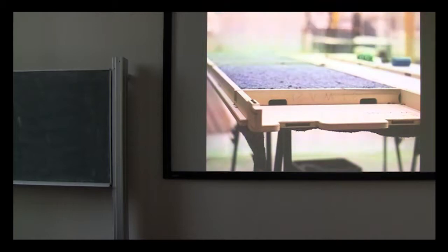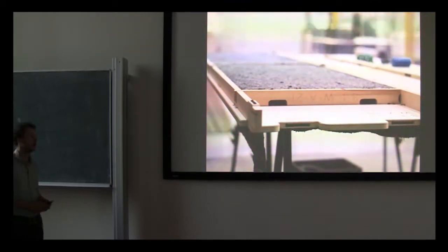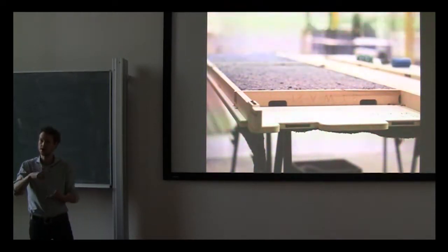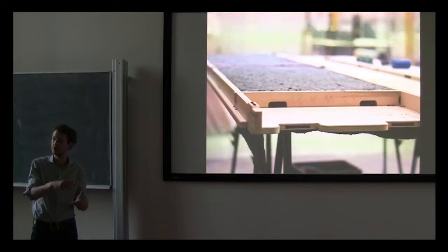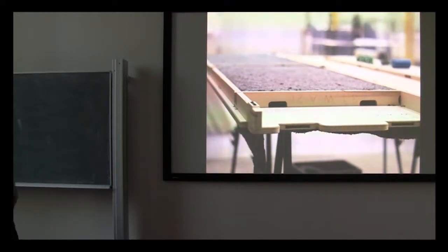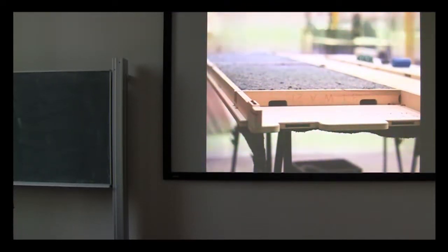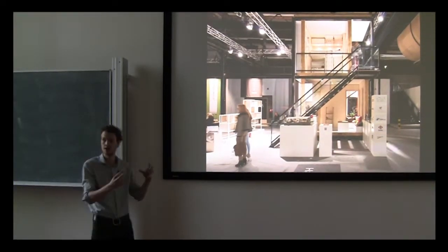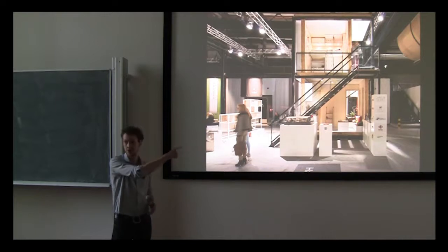And you also see that in the production process, we are able to completely integrate all the detailing. So these CNC milling machines have an accuracy of 0.1 millimeters, which makes it possible to create new smart connections where everything can be fit together, but also everything can be easily taken apart again. So it's only dry connections, also called friction fit.